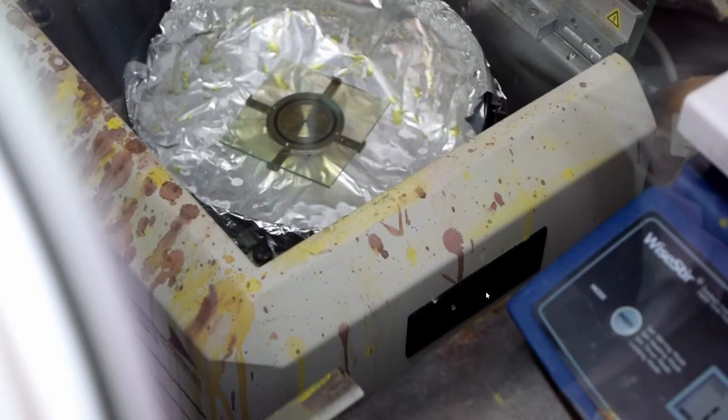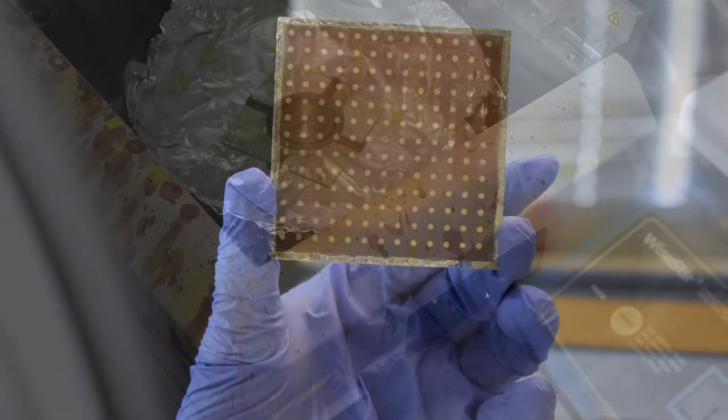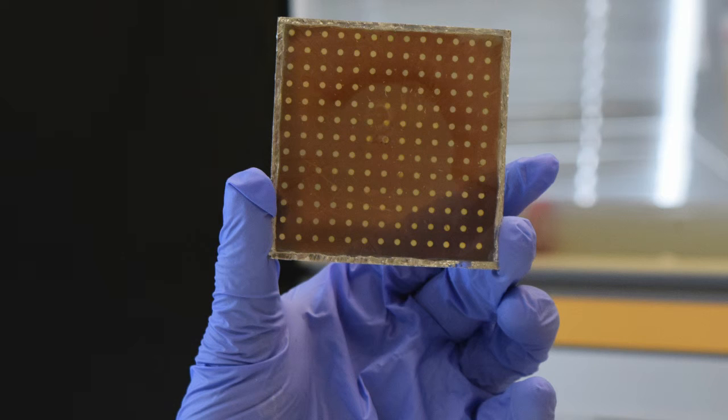Here we can see clearly that there is a change in the color throughout this layer. This may greatly affect the amount of light absorbed by any solar cells made from this material, and therefore affect the overall efficiency of these cells. Once a single or multiple layers are grown, we characterize the various physical properties of the material or device that are relevant to the solar cell performance in 169 points on a 13 by 13 grid.